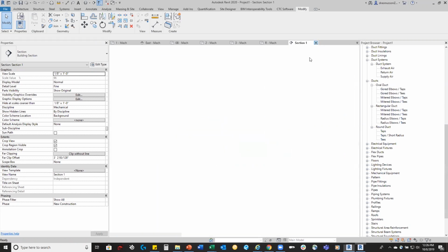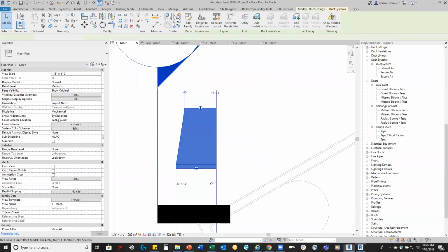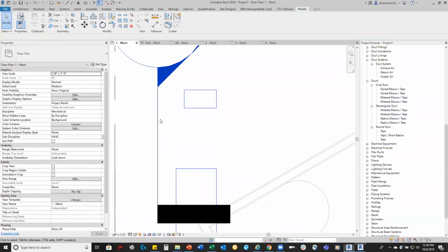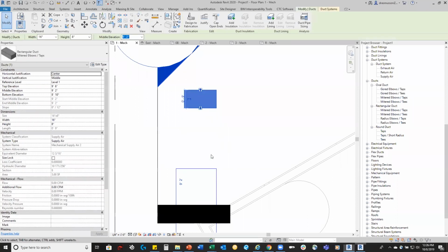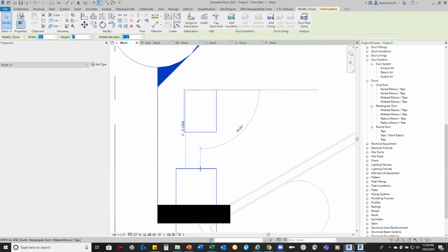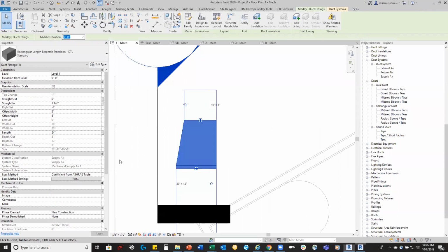Another way that you can accomplish this, everyone, without having to come in here and mess with numbers every single time that you want to adjust this particular fitting, is if we have this duct in the right spot like we do here, you can draw the smaller duct first, then drag that smaller duct into the bigger duct, and it will pop in that eccentric for you, so that you don't have to come in and play with any of the numbers to make it look more realistic with what you're doing. That'll be a nice little tip and trick for you guys to be able to use.